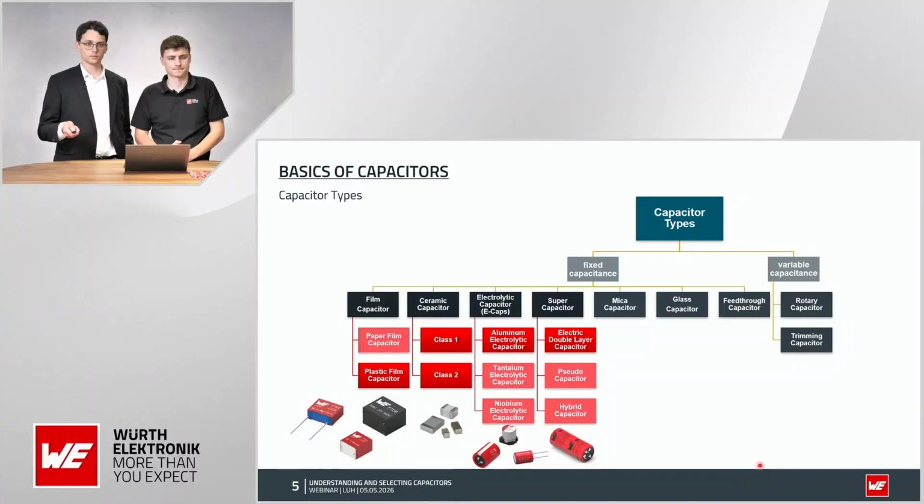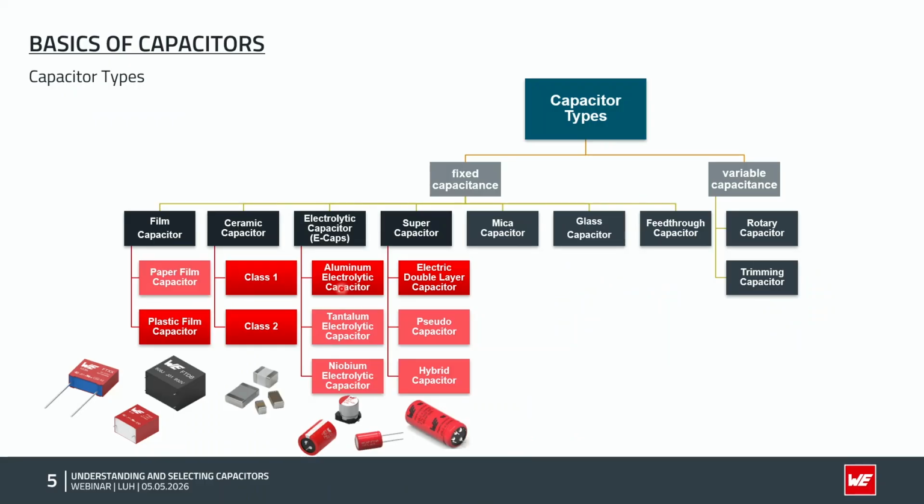Next question. In which group shall be polymer capacitor? Maybe if we speak about this one. I don't know if this was the question, but we can see that the polymer capacitors will be here in the electrolytic capacitor section, because the structure is that we use aluminum here, and we have the aluminum oxide, which is the main factor to describe how much capacitance we can have in this package. So therefore, it's here.